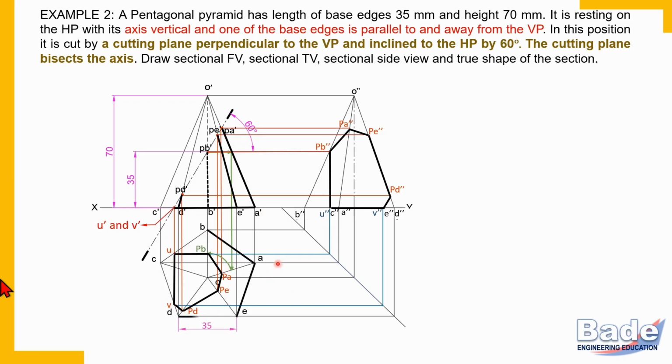So let's do that. This is how I have made the retained base edges dark, and then all face edges dark. Remember, inside the section there should not be any visible edge or hidden edge. Again, check here: the apex portion, that is above the section portion, is a removed portion.